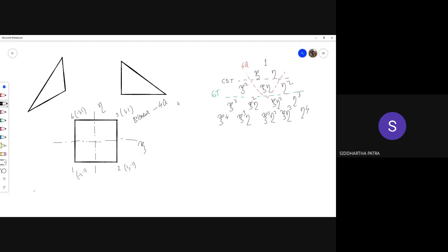Now when we move to a higher order element, the quad element goes from bilinear to biquadratic. Can you tell me how many nodes would be in the biquadratic quad element? For that, you need to think of how many nodes there were in the quadratic bar element.